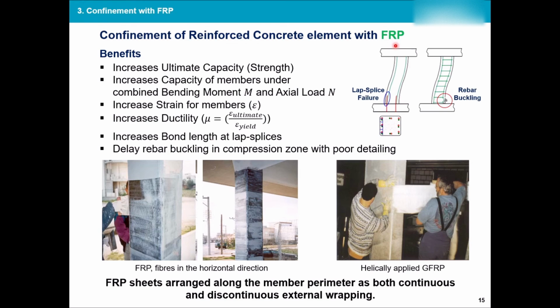This happens a lot in bridges. Imagine you have a bridge with the cars passing in the middle, so the axial load is actually in the middle while the columns are on the sides of the bridge. So there is a distance between that axial load and the center of your column. That distance will cause a phenomenon called, for example, P delta, and it will cause a moment on your section.